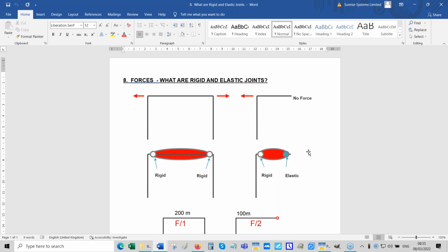It's the force that the fluid exerts on the pipe. The compensating force, or the force that's restraining the pipe, is not something that PIPENET can calculate, because the pipe could be supported here or there, or this could be connected to a tank.